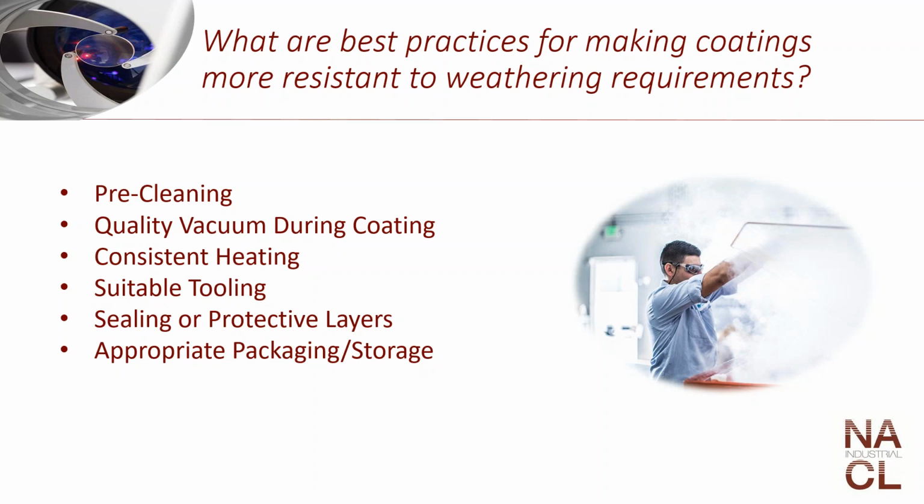And if your optic reaches a softening point, the film above it is going to model any surface irregularities that occur when that softening occurs. In glass, if you overheat your chamber, expansion and contraction can occur, which will affect your film. However, if you're consistent, and in glass, your expansion is a known and your film compensates for it, and then your contraction, when you pump back to atmosphere and go back to room temperature, is slow and steady and controlled, you won't have any surface modeling or irregularities.